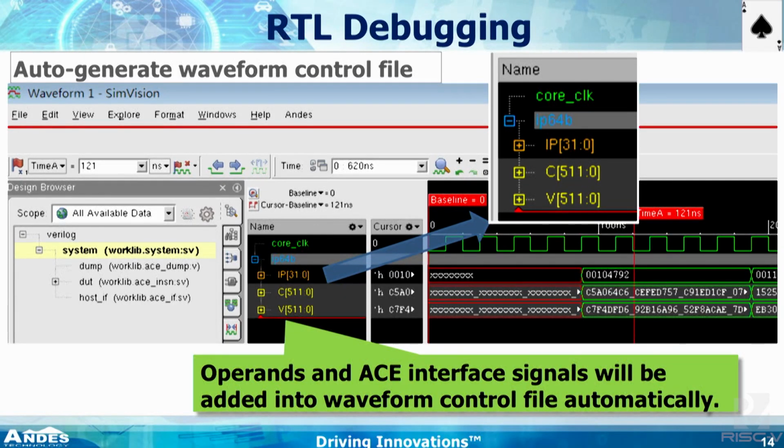And so the examples are kind of simple for presentation purposes. If you have complicated logic, for example, you can put a while or always loop there, everything except module begin and module end, because module begin is covered by the operand list. When you have complicated stuff, you may want to debug it, so the tool will automatically generate the waveform control file, so you can go there to see what's wrong with the signal, if you run the cross-checking in our environment and it detects some mismatch.